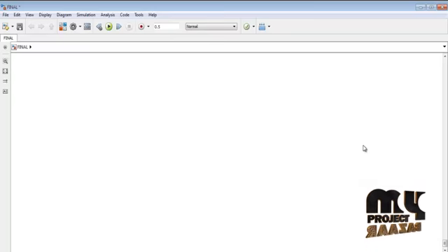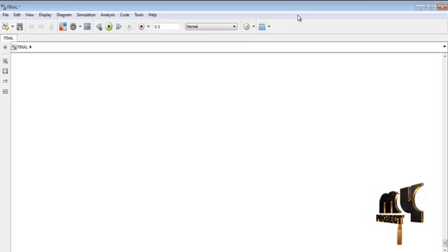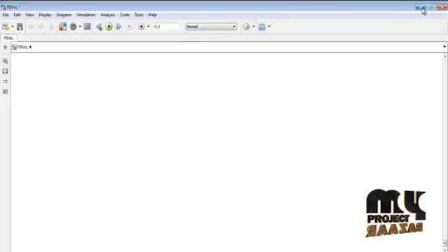In the Simulink library browser we mainly use two kinds of toolboxes. One is the SimPowerSystems toolbox, another one is the commonly used toolbox. From those toolboxes we get the elements and arrange them as per the given flow diagram. After that we click the run icon, then the simulation starts to run. When the simulation ends, we open the scopes connected to the corresponding measurement devices. Then the output is displayed in the corresponding area.